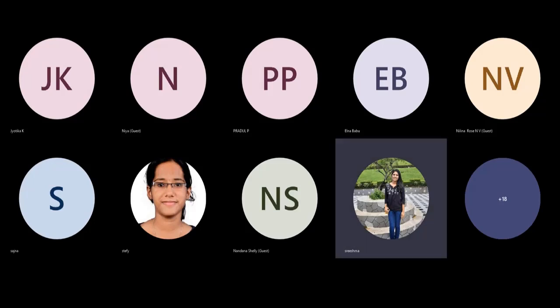There are some specifications that are typically considered when designing columns. The first one is column size. The size of the column is determined by the load it is expected to bear, as well as the height of the column. And the second thing is material. The material which is used for the column depends on the load capacity required and the environmental conditions. Common materials for columns include steel, concrete, etc.